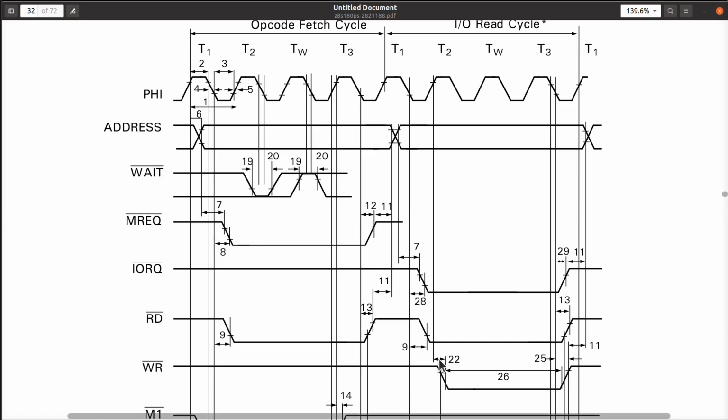So it turns out write can go low as late as this falling edge if you're running at 20 nanoseconds, because it will be 25 nano high, 25 nano low. Okay, so this diagram can be somewhat misleading because they draw the edge way over here, but it really could happen as late as on this falling edge. And that's why we want to make sure that our test bench is realistic and includes the extreme worst case values. And that's what we're going to see here.